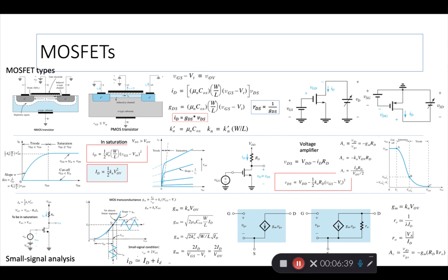All the amplifier behavior we analyze when the MOSFET is in saturation, and the other two zones are called cutoff and triode. Okay, all right. So the important thing is the overdrive voltage, VOV, is the difference between the gate to source applied voltage minus a constant VT, which is a threshold. A few other important relationships that I've tried to summarize here.